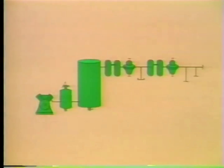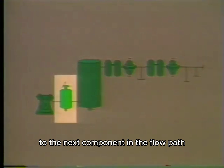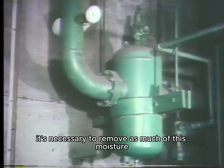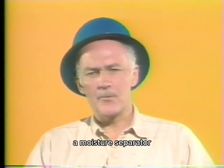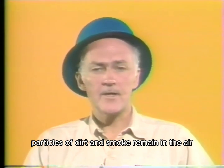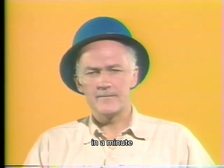in the plant. The compressed air flows from the air compressor to the next component in the flow path, typically a moisture separator. Because atmospheric air contains moisture, it's necessary to remove as much of this moisture as possible to prevent rust and scale buildup in the system. A moisture separator functions to remove most of the moisture suspended in the compressed air. But often, other contaminants, such as lint, particles of dirt, and smoke, remain in the air. We'll discuss how these contaminants are removed in a minute.